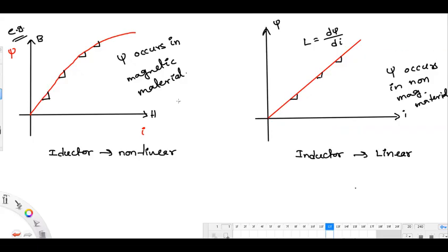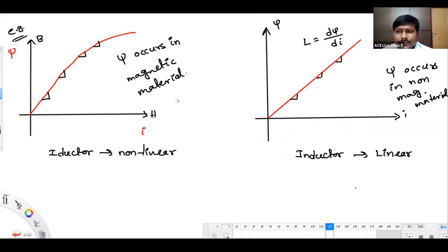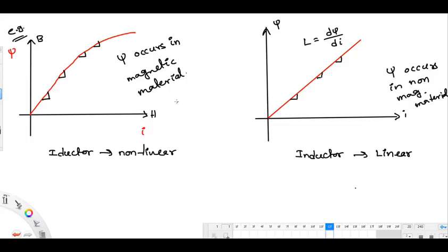And sir, regarding the measurement of R that you said we measure: you supply some power, you calculate the output power, and from the losses you can calculate R. Yes. Then in measurements there are AC bridges. If you take some unit length, around 1 meter, and use an AC bridge to calculate the resistance for that proportionate length, that will also give RAC, no, sir?